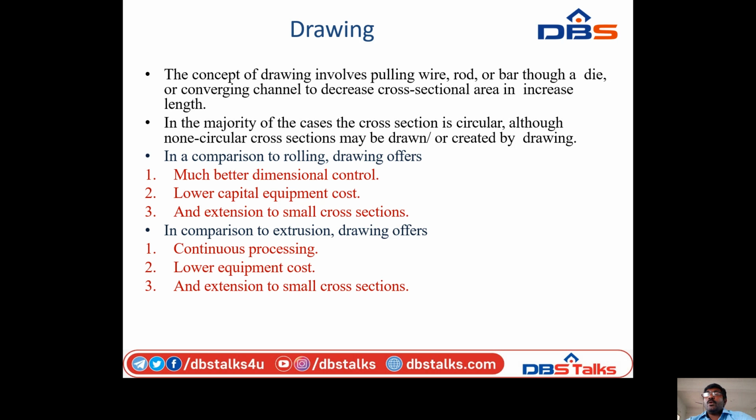In comparison to rolling, drawing offers much better dimensional control, low capital equipment cost, and extension to small cross section. In comparison to extrusion, drawing offers continuous processing, lower equipment cost, and extension to small cross section.